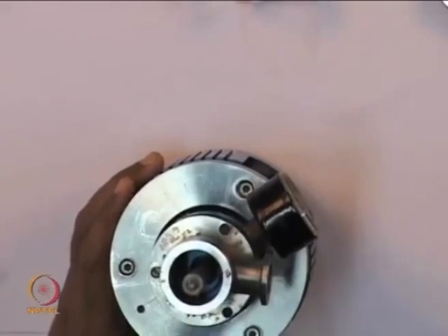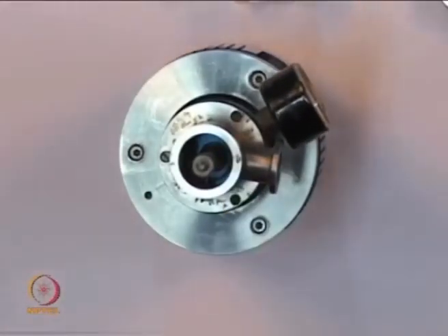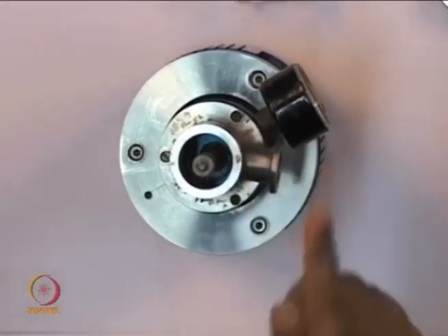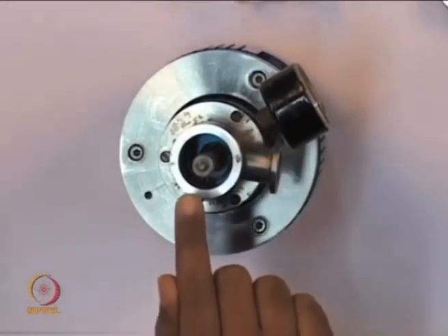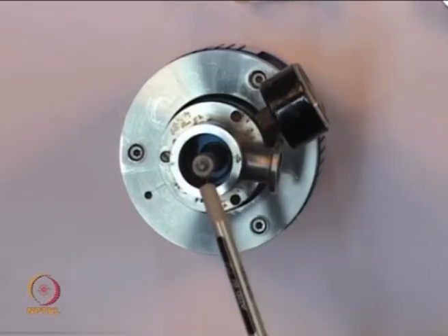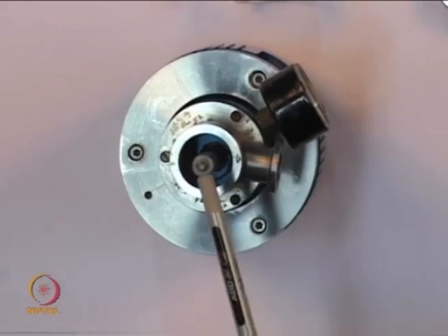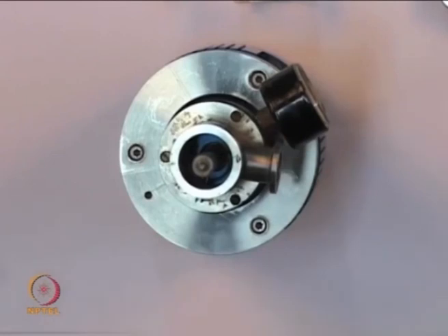What you can see at the top is the cold finger. If I want to cool a certain object, I have to conductively couple that object to this cold finger. This cold finger is going to generate around 80 Kelvin temperature. For example, this cooler has been designed to produce around 0.5 watts at 80 Kelvin to cool some other object.